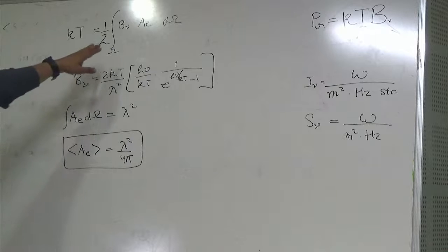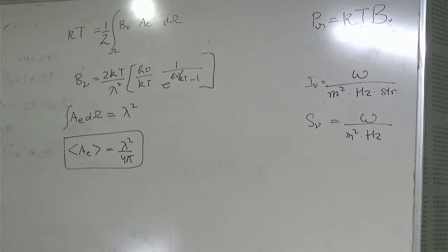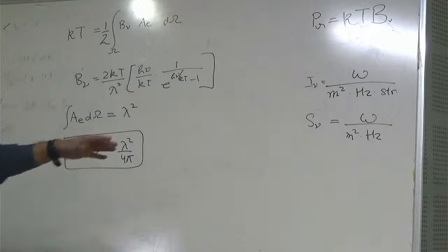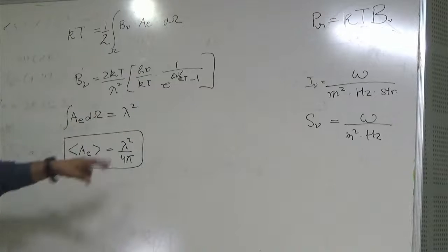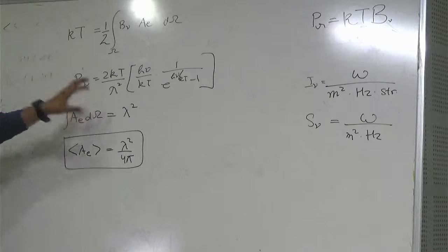And this is simply coming from here because we wanted to convert intensity into power. The nice thing that you see here, effective area of a dipole, or for that matter any antenna, only depends on the lambda. It's not the geometric area at all. It might be related, but it's not really the geometric area. You can't just take the length and breadth of the dipole and say that's my antenna area effectively. Because what you're getting is this relation. So I basically took some average value and made the integral of d omega to be 4 pi.